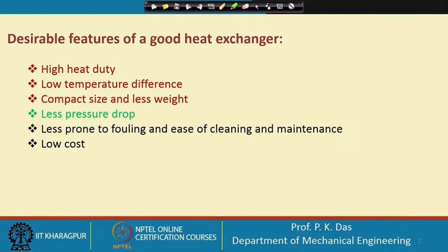So, the 4 points mentioned at the top, those are very important as far as the thermal hydraulics of the heat exchanger is concerned. So, we have to have high heat duty. We desire to have a low temperature difference between the two streams. We obviously want our heat exchanger to be small and lightweight, and there should be less pressure drop. So, with these 4 points, let us proceed.